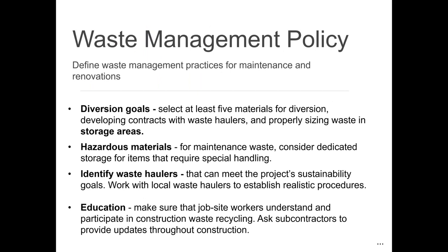Your waste management policy, you want to define your waste management practices, so your diversion goals. You're going to have your 5 materials that are going to be most commonly collected as waste for that project. You're going to develop contracts with those particular waste haulers that can accept and divert those products. And you want to make sure that you have a properly sized waste storage area. That's just saying the waste that's collected at the building, rather than being piled out in the back of the building in a disorganized manner, how can you plan for it and make sure that those materials are stored appropriately so they can successfully be recycled or diverted?